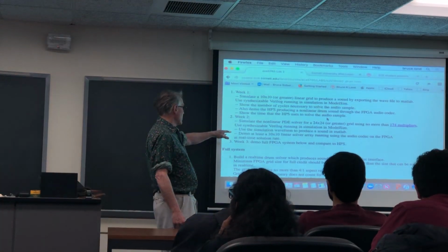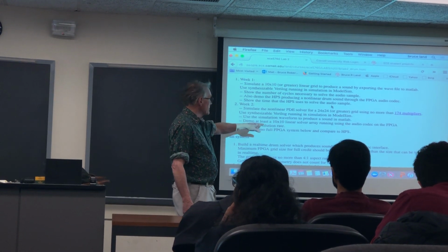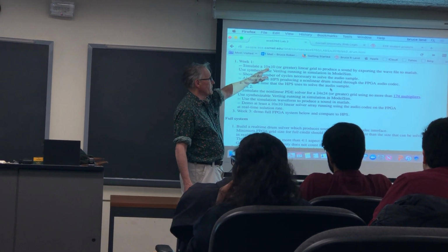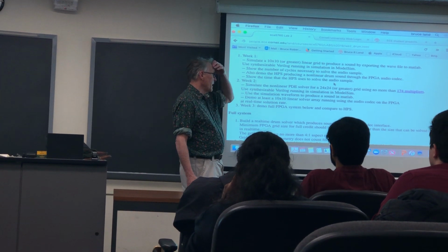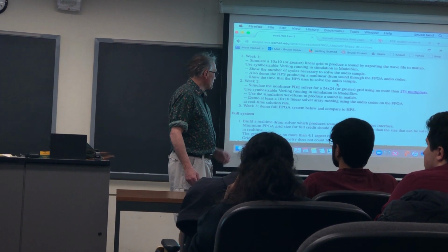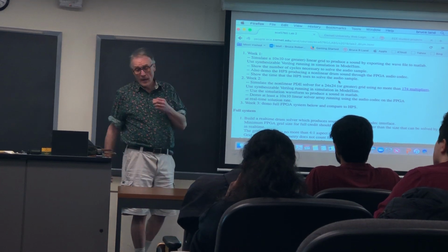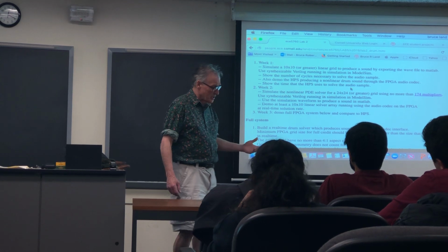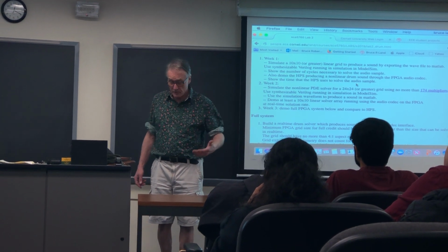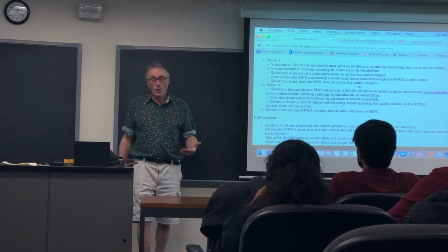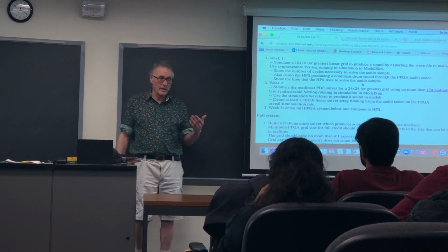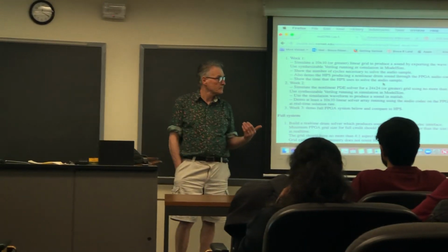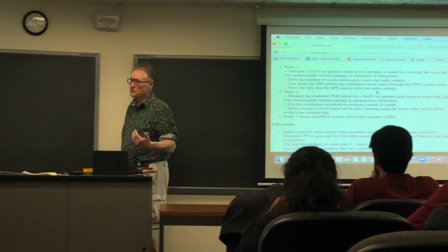And to demo at least a 10 by 10 linear solver, in other words, what you debugged last week in ModelSim, should now be embedded on the FPGA and produce sound. So presumably that's going to be on the FPGA and either running under the control of a busmaster, or sending data back to the HPS, which will then feed it back to the audio codec. Any questions on this?